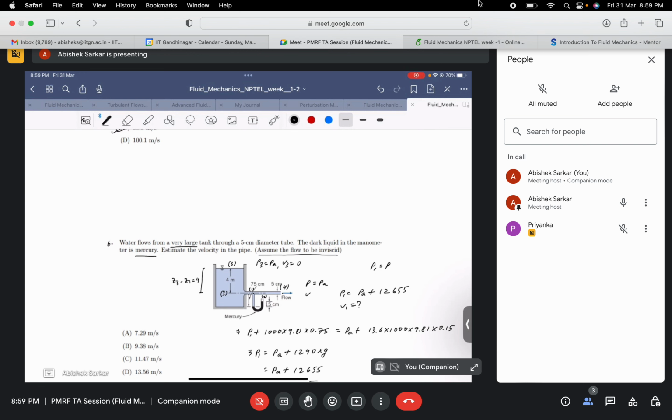Okay, these other points, I won't say these are wrong. You can apply here also, but the thing is that you don't know the exact or accurate value, I would say only approximately correct values, of the pressure and velocity at these points. That's why it's not a good choice of points for implementing the boundary equation.